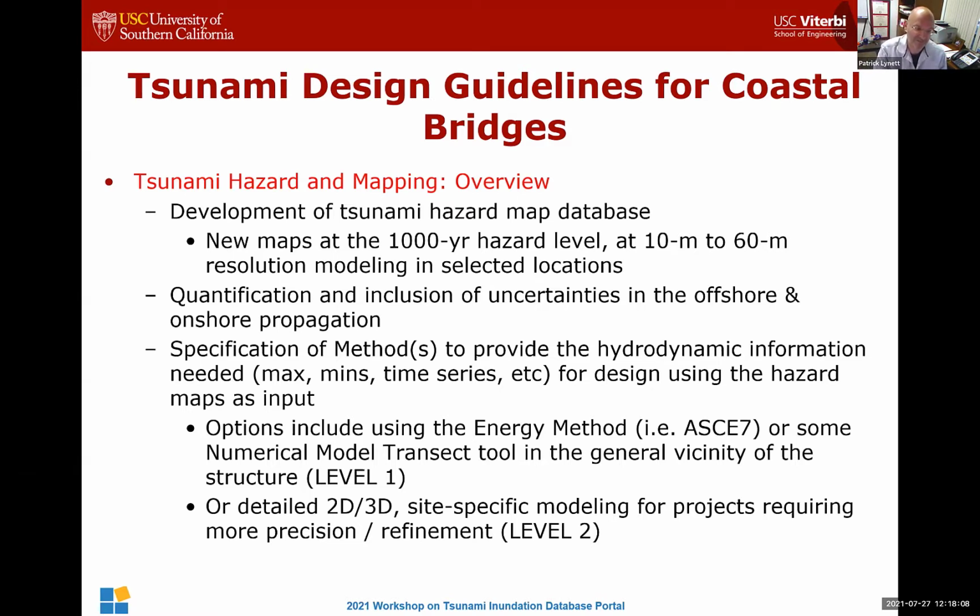And then that last part, which is really the important piece, is the specification to provide the hydro information that is site-specific to the bridge project. There are two main options inside this bridge guide spec. Level 1, which requires you to go to the energy grade line analysis, which I'll introduce and talk about quickly. And then level 2, which is refined site-specific modeling where you are doing 10 meters or less resolution modeling for your particular area of interest.